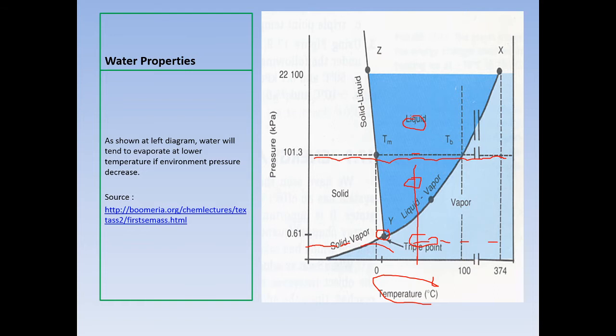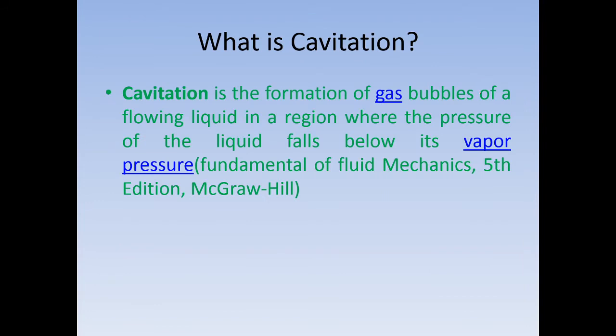So in relation with cavitation, as we have talked before, we have to be careful that the lower you make the static pressure at the suction, based on the operation, the easier the water will become vapor. And when water is vapor, it is really dangerous to the pump.